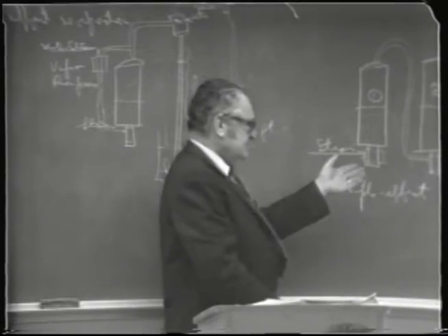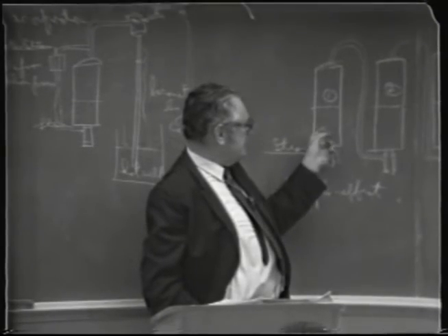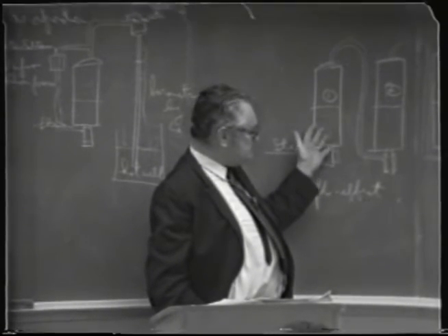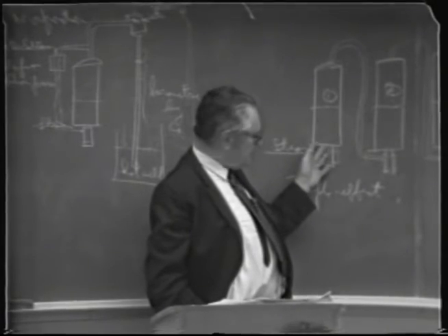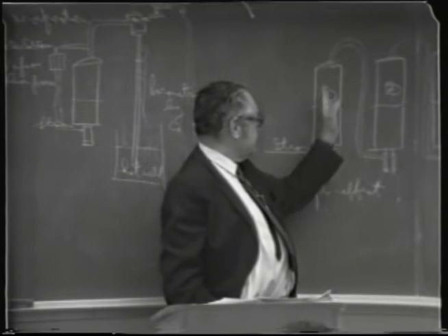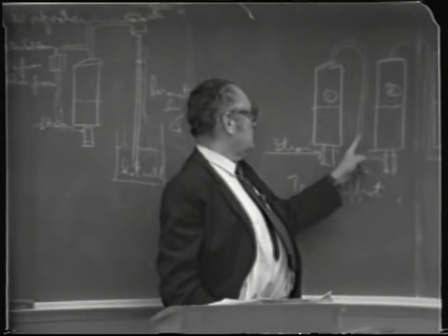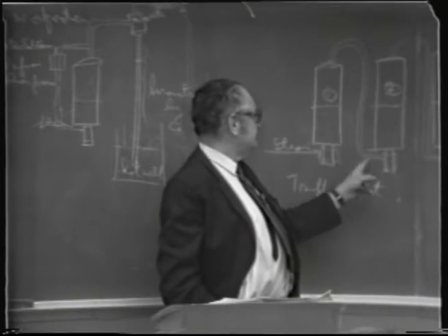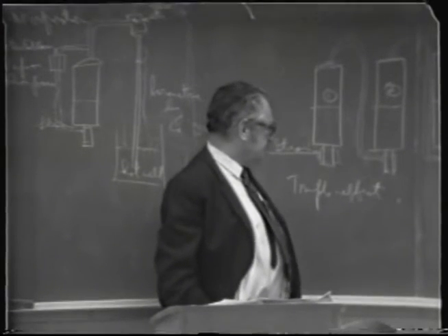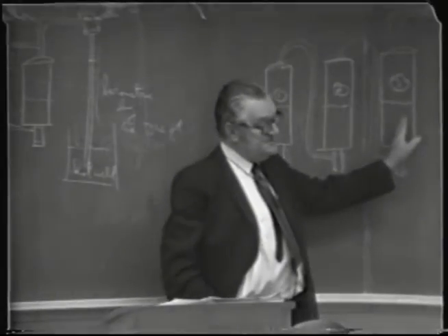But without going into any great detail here, it's obvious then that you have to have a fairly high pressure in this, or a high boiling point in reference to this. Otherwise, you're not going to have any boiling point difference between this vapor and the boiling point in here. So this has to be at a lower pressure than this one, and this has to be at a still lower pressure.